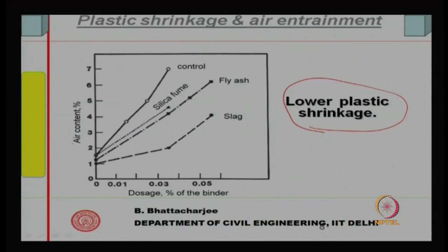Now, if this air entrainment percentage gets disturbed, then the performance of mineral admixtures in cold climate or where freezing and thawing is possible could be questionable. But let us see what happens. So, obviously there is a reduction in air content with all the mineral admixtures. If I have increased the dosage of the binder, I find that there is a reduction in the air content, whereas the control gives you much higher air content, they all reduce the air content.